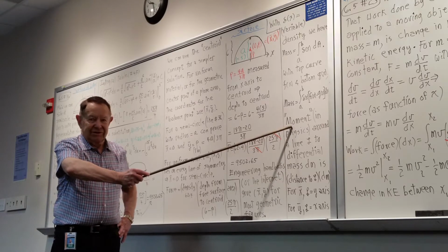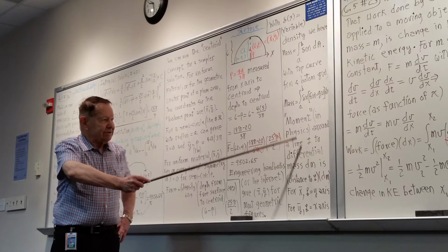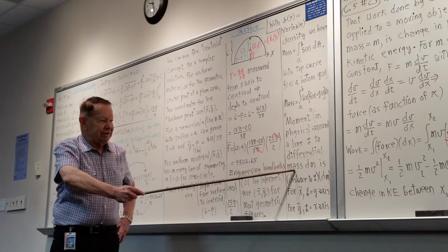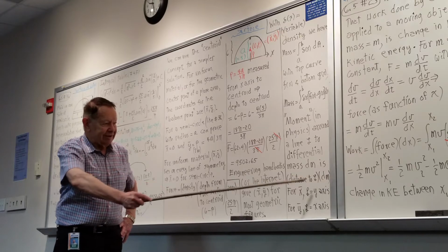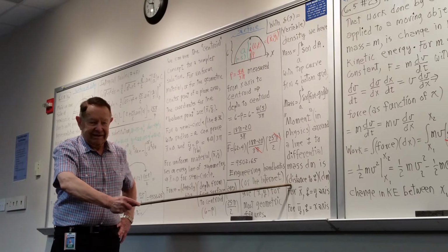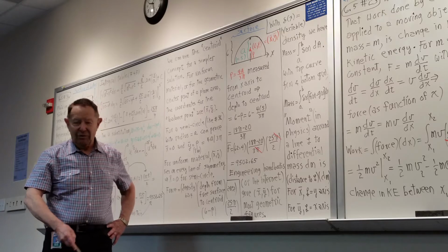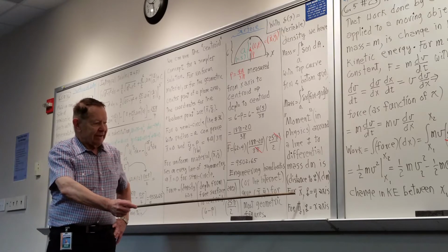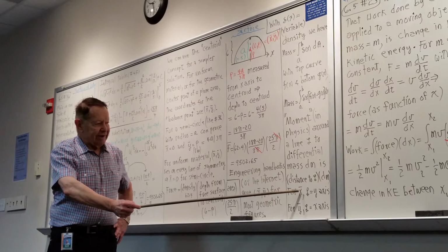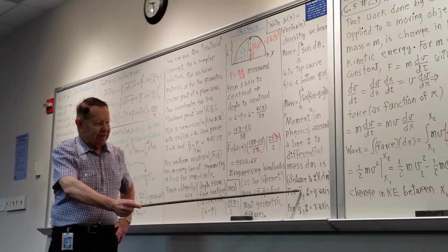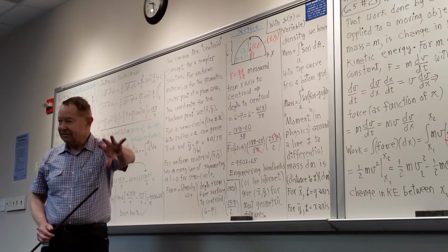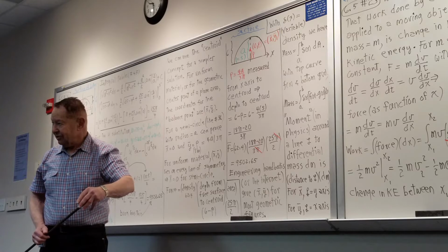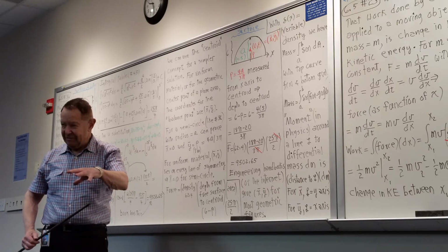This is also what you call a moment. And so the moment around a line, for a differential mass, is the distance from wherever your differential mass is to whatever the line is that you're measuring the moment around. So what we're trying to get is the coordinates x bar and y bar of the center of mass. That's the balance point, like I was showing you with the homework papers and the pen.